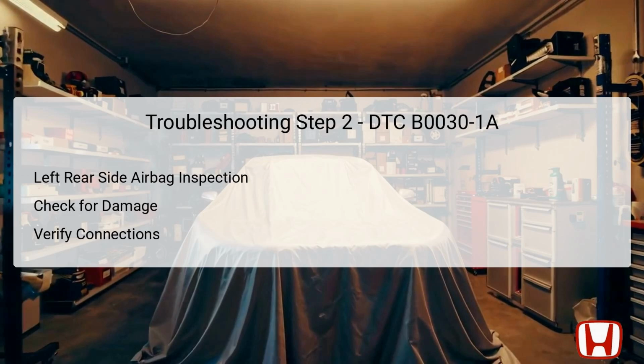To start, ensure the left rear side airbag inflator connector is disconnected. This is crucial for safety before further examination. Look for any visible damage, such as tears or physical deformities, which may impair the airbag's function. It is also essential to verify that all electrical connections are secure and free from corrosion or dirt.